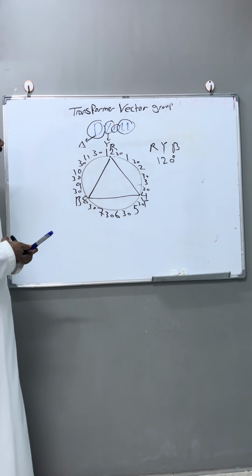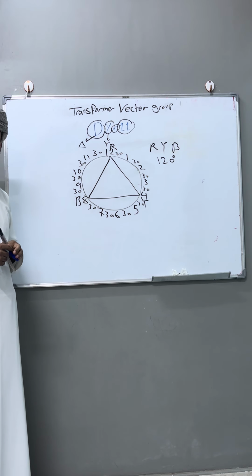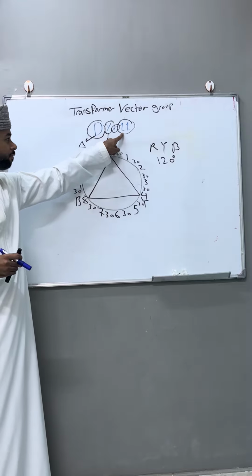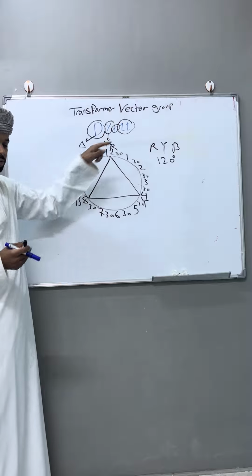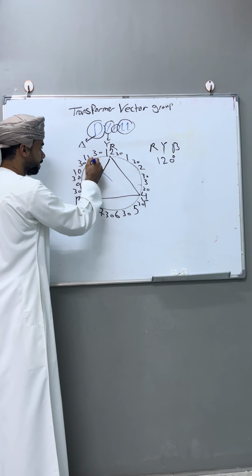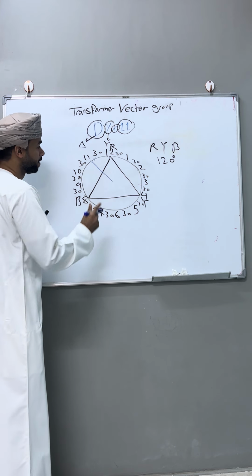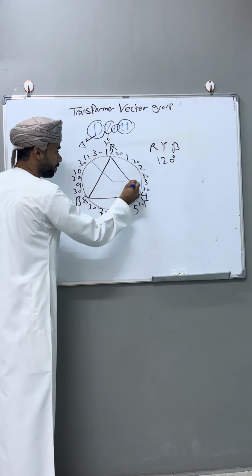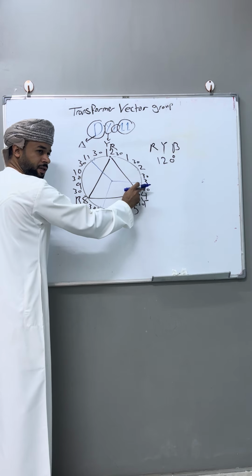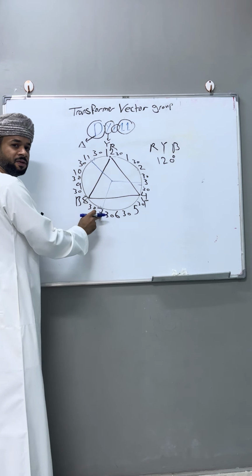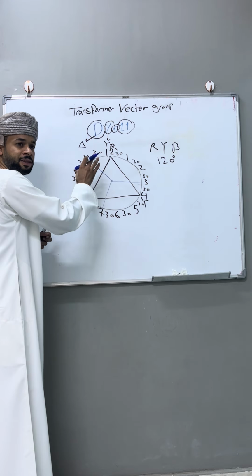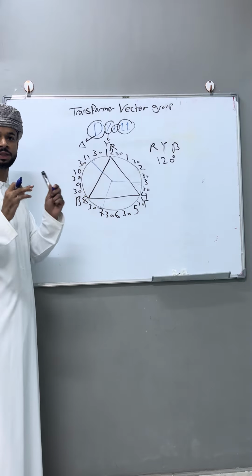Okay. Now let's draw the Y connection, or star connection, but for the star connection the reference is from 11, right? From 11, because the vector group we have here is 11. So this is the 11 here, like this. This will be R small, R secondary. So this R will go to 3 to 7. Now let's check. From 11 to 3 it is 120 degrees. From 3 to 7 it is 120 degrees. From 7 to 11 it is 120 degrees. Now I have drawn the delta and star with a phase angle of 120 degrees.